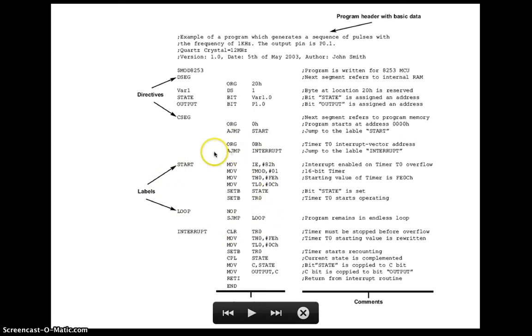So whenever it's calling the loop, it will go to the loop. This is how it goes. If there is a jump to interrupt, it will go to the interrupt, and after finishing the interrupt subroutine, it will go back to where it stopped and continue at the next line. The same happens with delays, either software delays or even pure hardware delays.